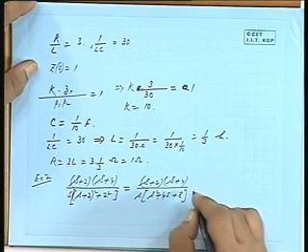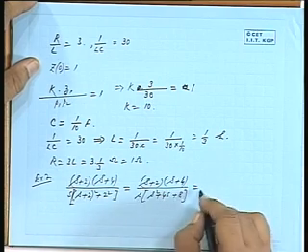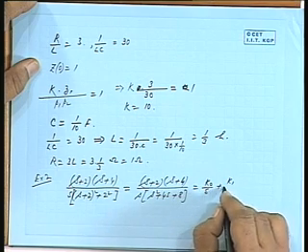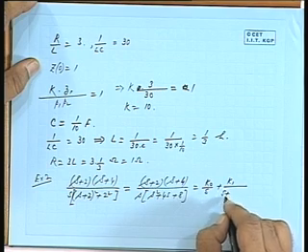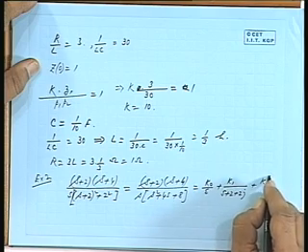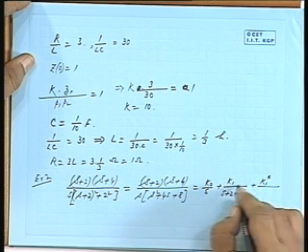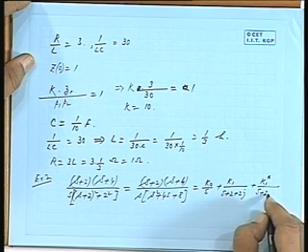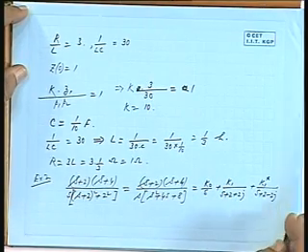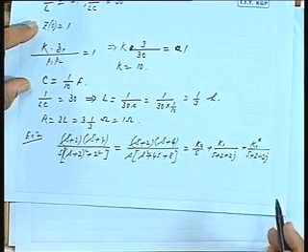What will be the pole zero distribution? And suppose I want to break it up as some k0 by s plus k1 by s plus 2 plus 2j plus some k1 star. This is a residue corresponding to a complex root. So the corresponding residue for the other complex root will be the complex conjugate of k. We will see that. So how do you evaluate k0, k1 and k1 star graphically?